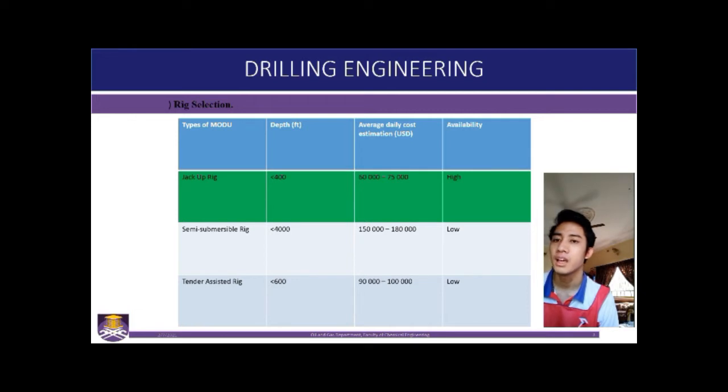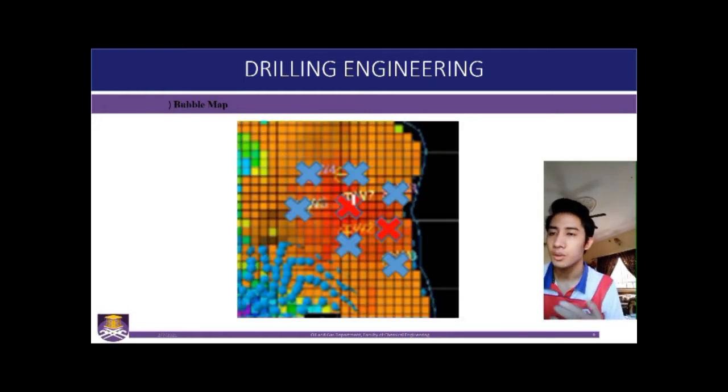which makes the jackup rig more preferable compared to the other two rigs. Based on the water depth, Gelama Merah Field is considered shallow water. Therefore, water depth shall not be an issue as a jackup rig can be operated up to about 400 feet. The data of the well location has been provided by the reservoir department.